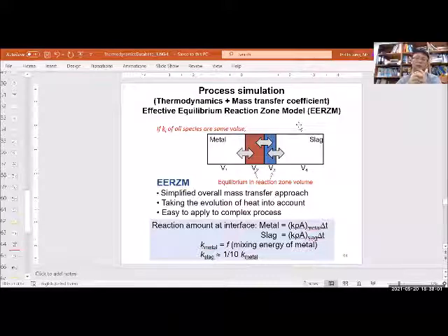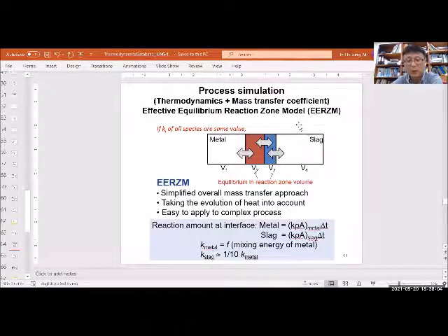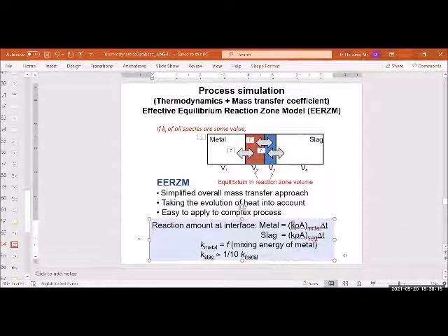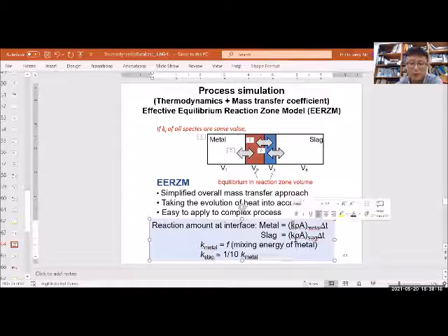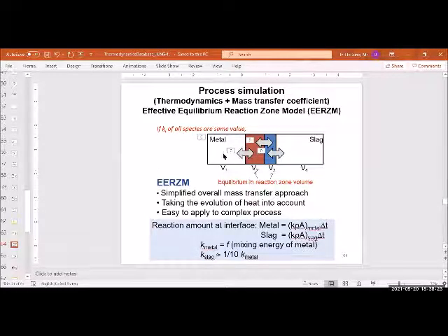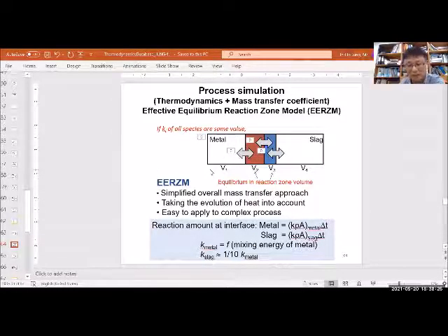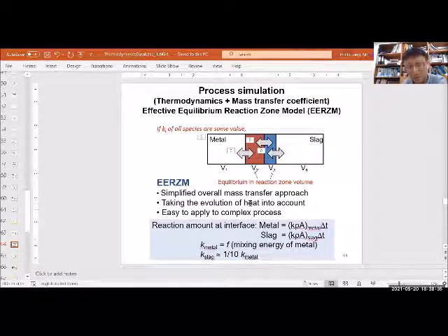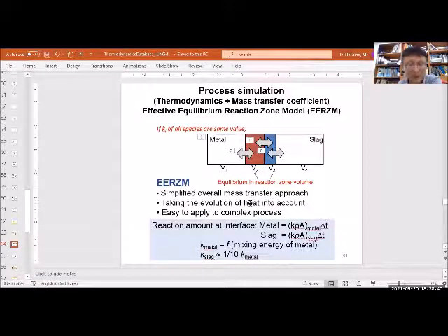It's a very good question again. Typically this Ki, the mass transfer coefficient, is different depending on the element. However, if you look at the real values, the order is almost the same. And also, if you are in a very static, almost no-stirring condition, then of course the intrinsic diffusion of the element inside the metal determines the mass transfer coefficient, and it is by element.